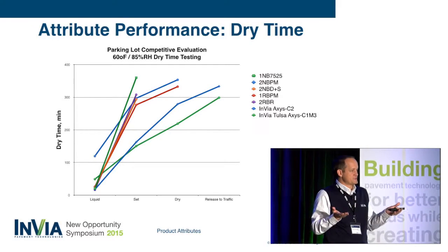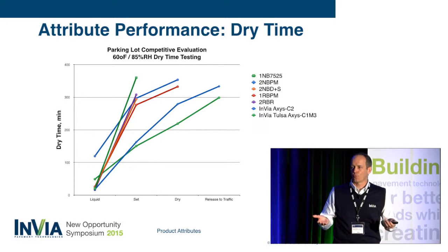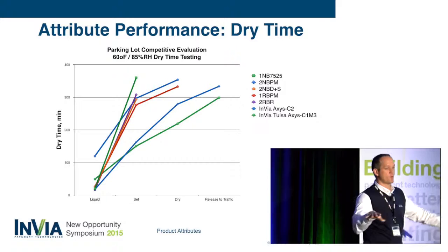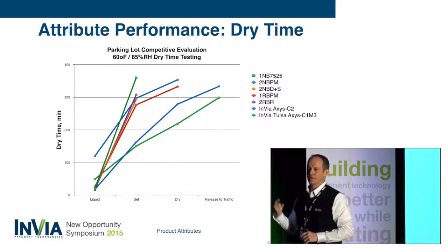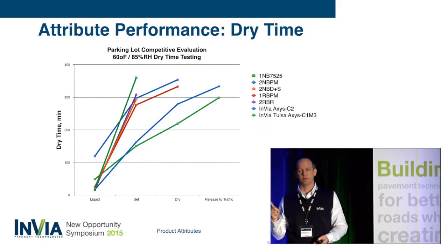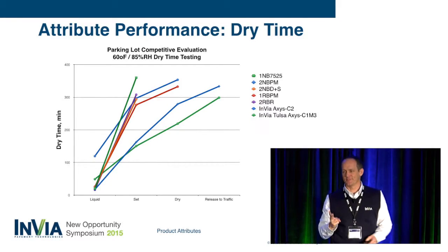Once the water's on the surface, you guys can all go out to the internet. You can find the equation for water evaporation. It's based on 4 key variables. And I'm talking about once you just have water on the top, you have the air-water interface. It is the surface temp, which is the pavement temp. If you guys have an IR gun, you can shoot it and know that number. It's the air temp. Look at your phone. Everyone has air temp.